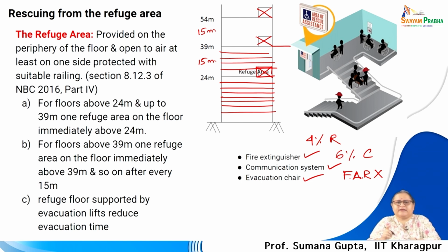So, usually in case of a fire, all electrical systems collapse or they are switched off, so that no further damage happens, but certain emergency lines remain active, of which this fire rescue lift refuge area connection through a staircase becomes mandatory. So, usually refuge areas are collection points very close to or within a staircase system, from where the firemen can actually do some rescue operation.